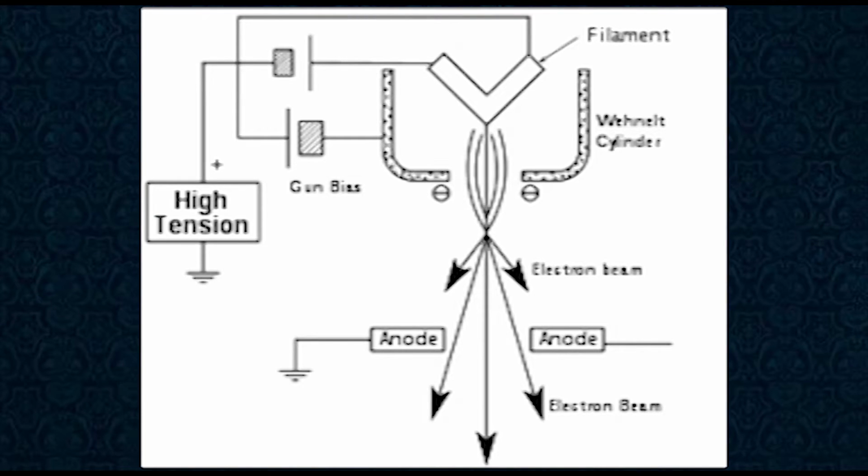The electron gun is formed from several components: the filament, a biasing circuit, a Wehnelt cap, and an extraction anode. By connecting the filament to the negative component power cable, electrons can be pumped from the electron gun to the anode plate and TEM column, thus completing the circuit.